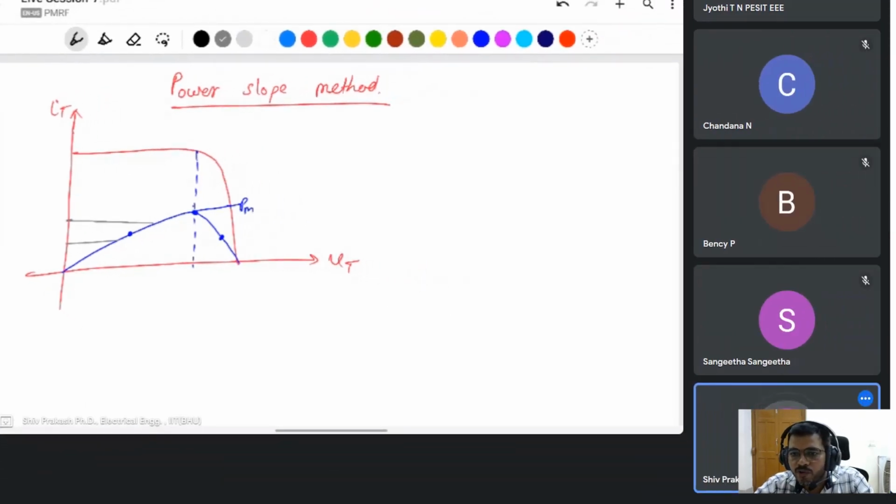if you have a question, then please share the question so I can understand what you are asking. If Ro is not given, but power is given, how to calculate the load resistance? Which power is it, input power or output power? If the input power is given, then you can also calculate the output power, equal to the input power in ideal cases.